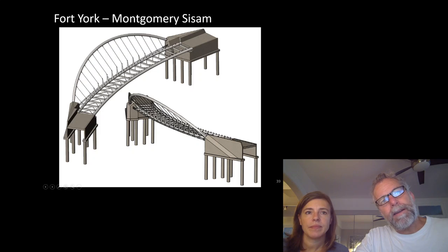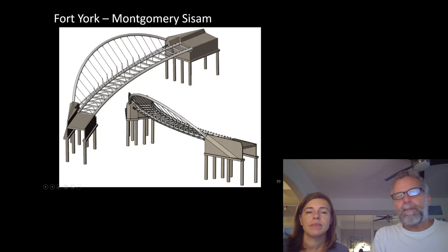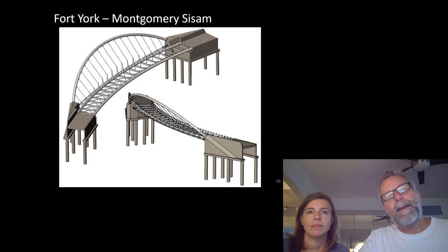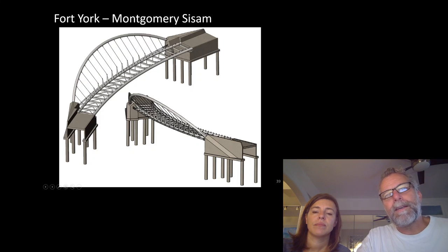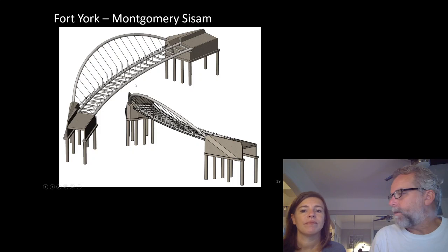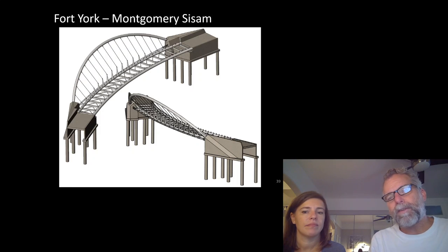You see we've got in our deck, we have these two big pipes, and so those two pipes make the deck torsionally rigid. And then ours was a big curved pipe arch. You know, this is one of the lessons learned. We felt that the bridge needed to satisfy the most stringent vibration criteria, and so this is quite heavy.